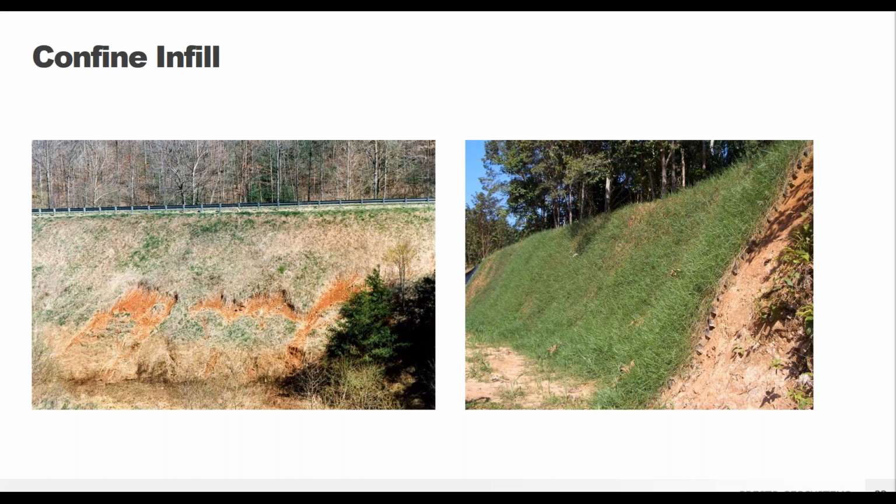The system provides a way to fully vegetate slope surfaces that otherwise couldn't support sustainable plant life, and increases the overall slope stability by interlocking with the vegetated root zone. And stone and concrete materials can also be confined within the GEOWEB panels on slopes that would normally be too steep. The stone would just slump all to the toe of the slope, not with the GEOWEB panels.